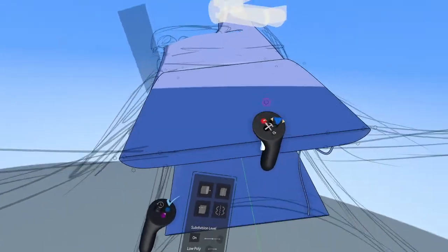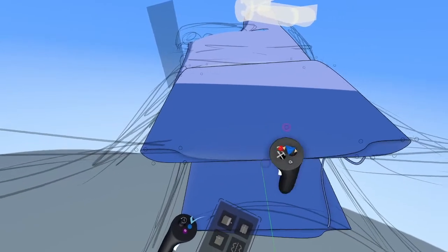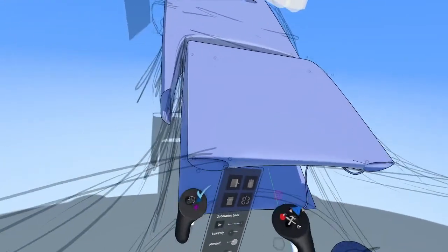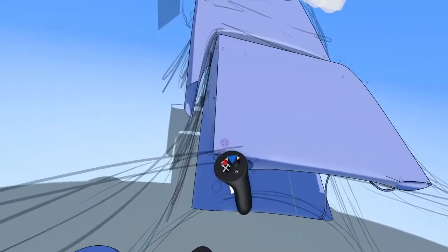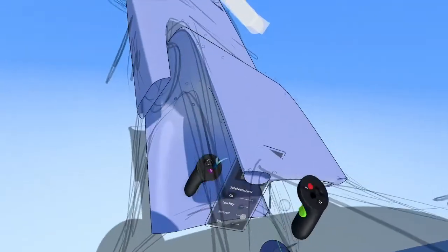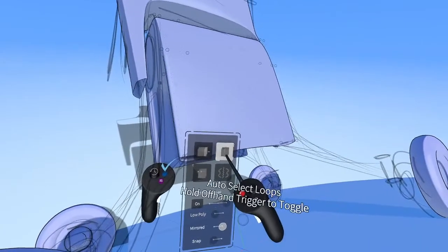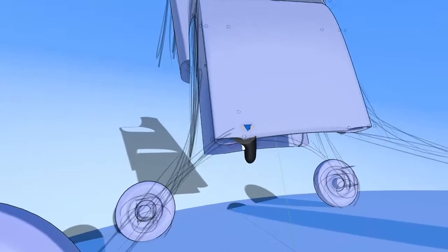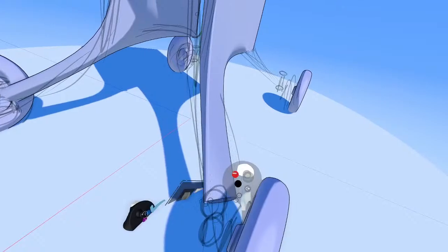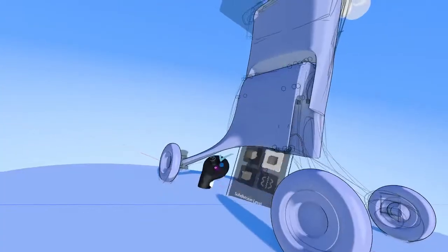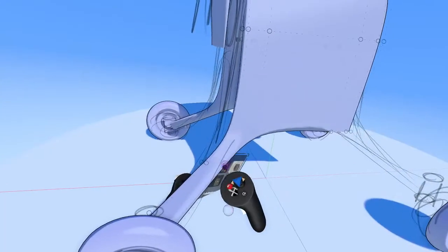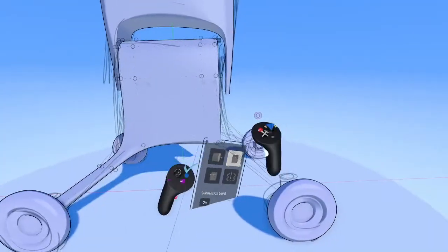And now grab just this edge and connect the middle part here, and then use this little hole that I have here to actually shape the legs here. So I'll turn on Auto Edge Loop and grab this loop, press the pointer finger trigger, and duplicate it out like this. And I'll just stretch it out like that. We'll do the same thing up here.